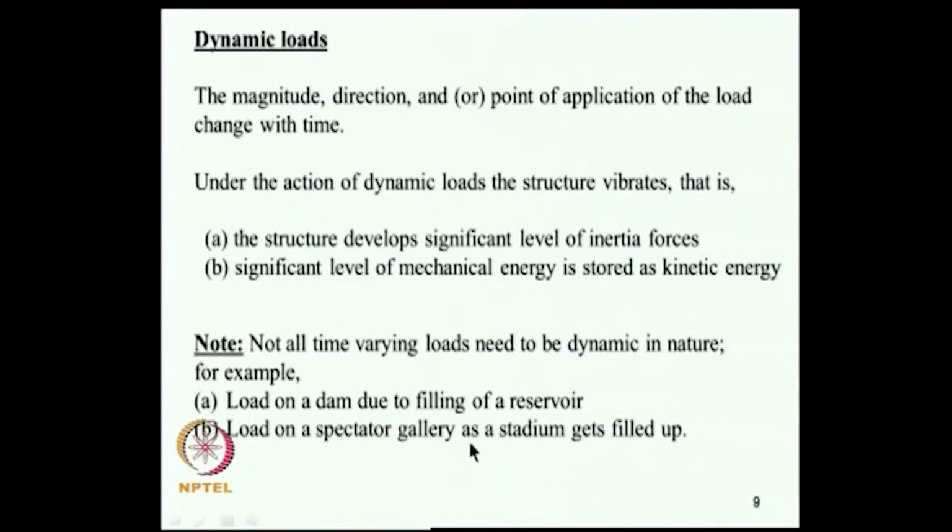Similarly, load on a spectator gallery as a stadium gets filled up, here too the time varying nature of the displacement and hence consequent velocity and accelerations are low. That means the time variation of displacement is so slow that acceleration levels are very small, therefore, little of inertial forces are mobilized in these problems. Therefore, we cannot call these problems as problems in structural dynamics.